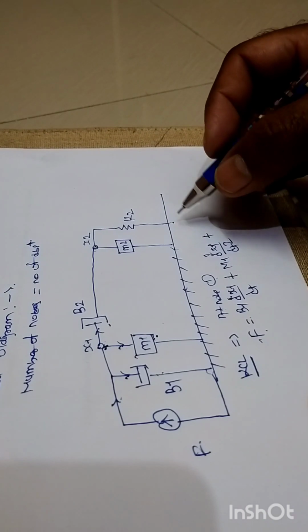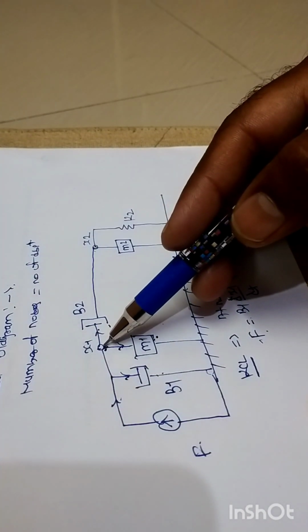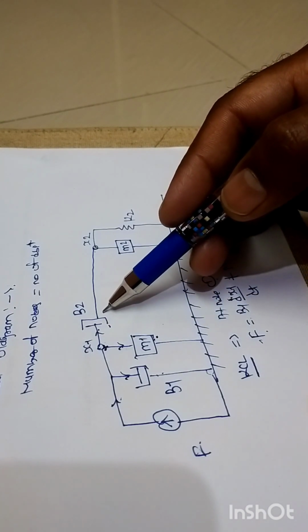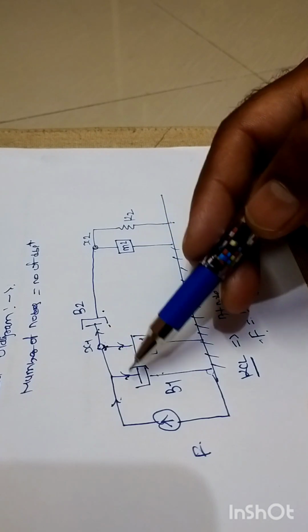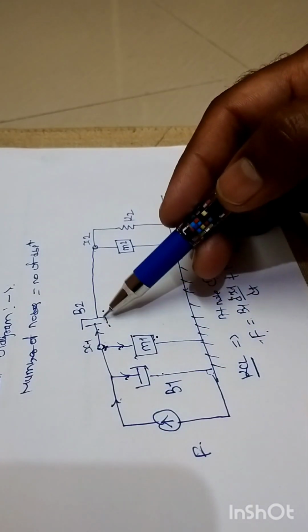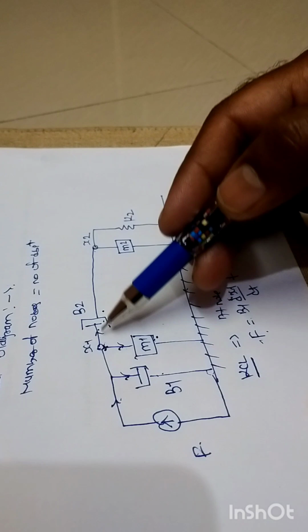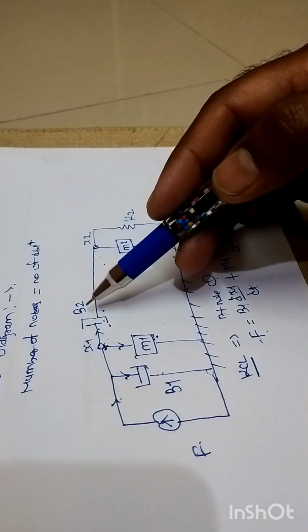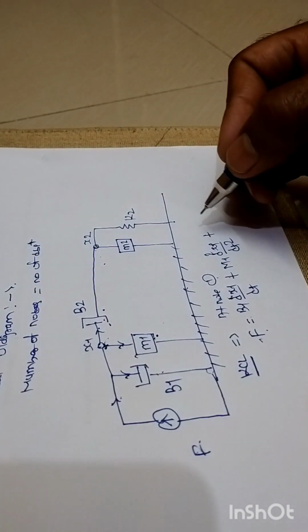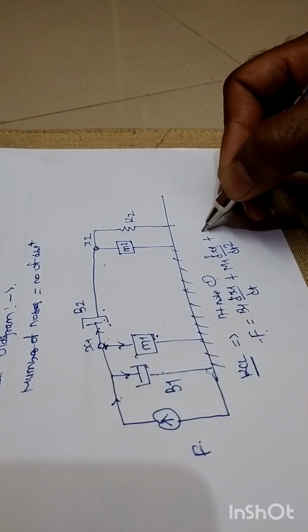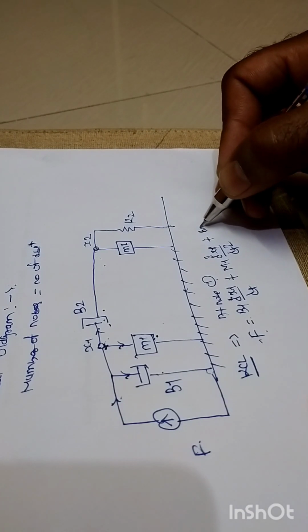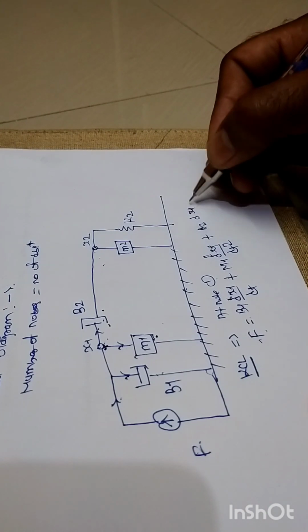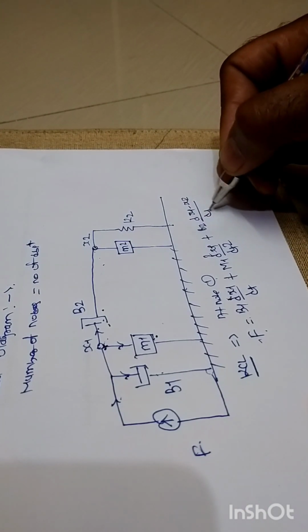Plus the remaining, the third branch associated with this x1, in which this damper B2 is connected, right? So as you can see, this is the direction of applied force. So the direction of force belonging to this branch is outgoing from this node. It goes from x1 to x2. So the overall displacement through this B2 with the help of this system equation will be what? As I told you earlier, B2 stands for velocity, means first order differentiation. So it will become d x1 minus x2 upon dt, right?